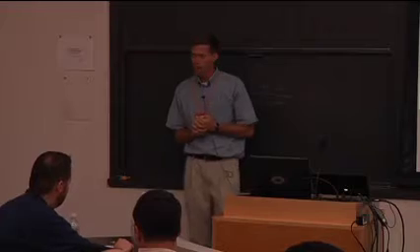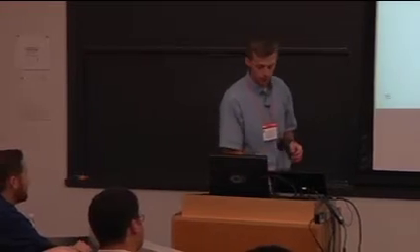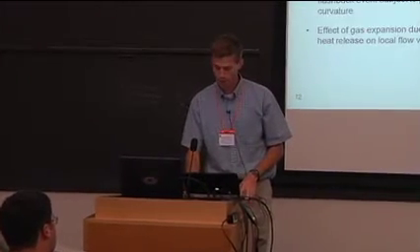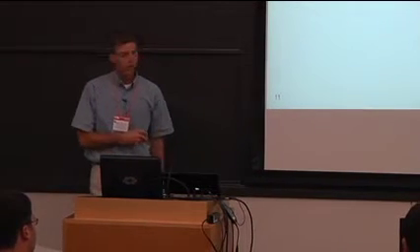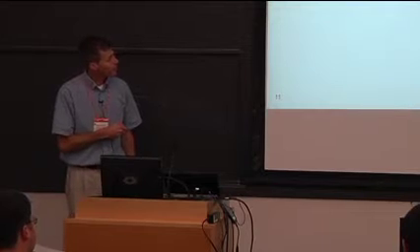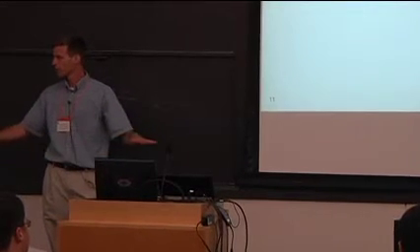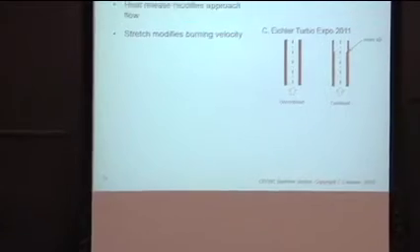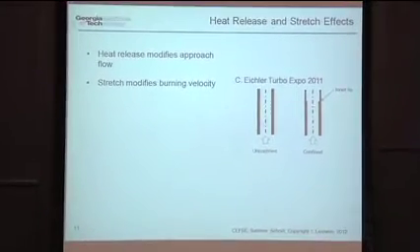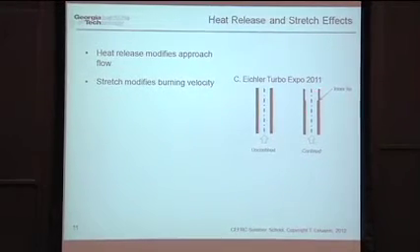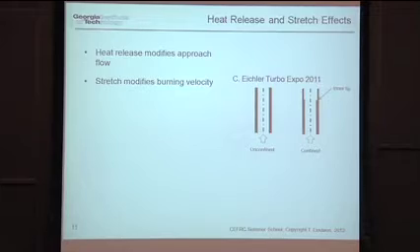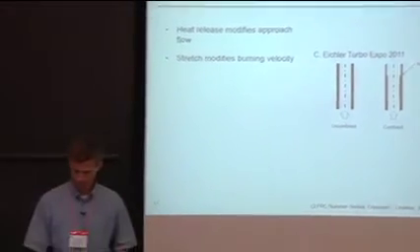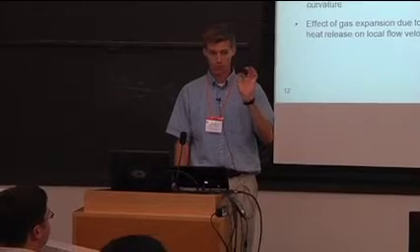Okay, so the reason is in the unconfined case, you have such a massive adverse pressure gradient at the outlet that the back pressure that the flame imposes on the boundary layer is totally negligible by comparison. Here, the flow is nominally a zero pressure gradient flow, and so that adverse pressure gradient the flame imposes on the flow totally changes the problem. So the key point is flames cause this local back pressure.